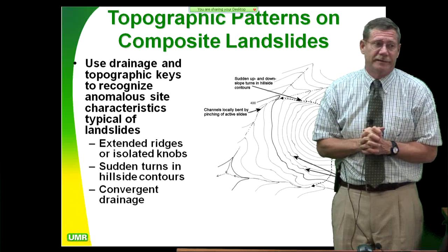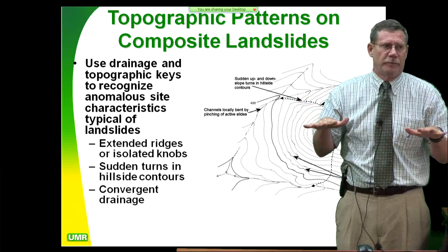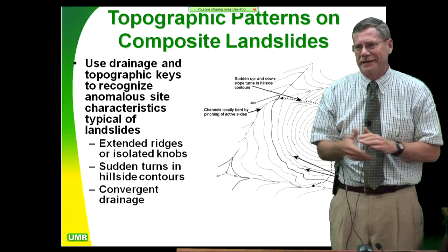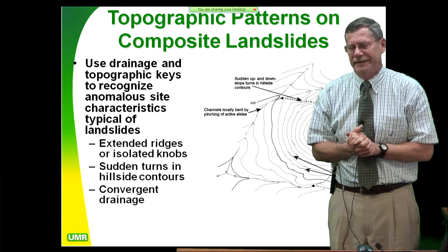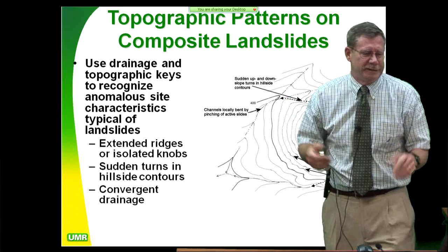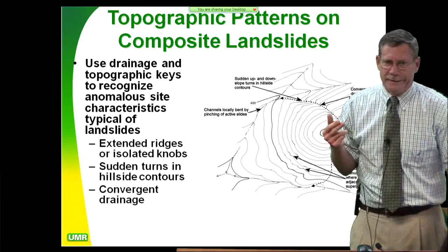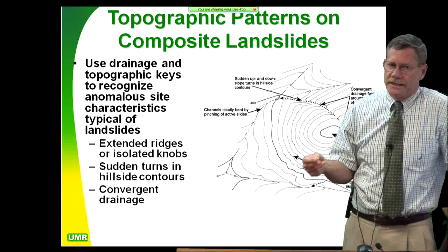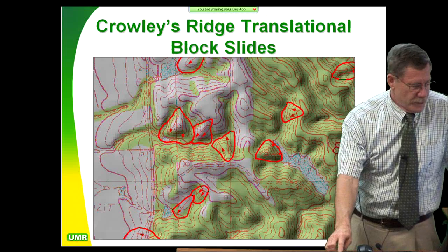Well, but it's a big lake. And that's a big change in pore pressure. If you're going to go an inch a day and you just keep doing it and doing it for a couple hundred days, that's a couple hundred inches. That gets to be significant. So that's when a lot more emphasis started being put on drawdown effects on slope stability.